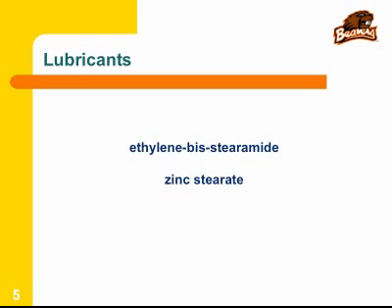So hydrocarbon chain, carbon hydrogen, which is relatively lower molecular weight, typically about 16 to 18 carbon atoms in one of them. In this case, there are two of them, and in this case also there are two of them. And so the presence of the hydrocarbon, it's oily, it's waxy, and so that property on the one hand is able to reduce the friction.